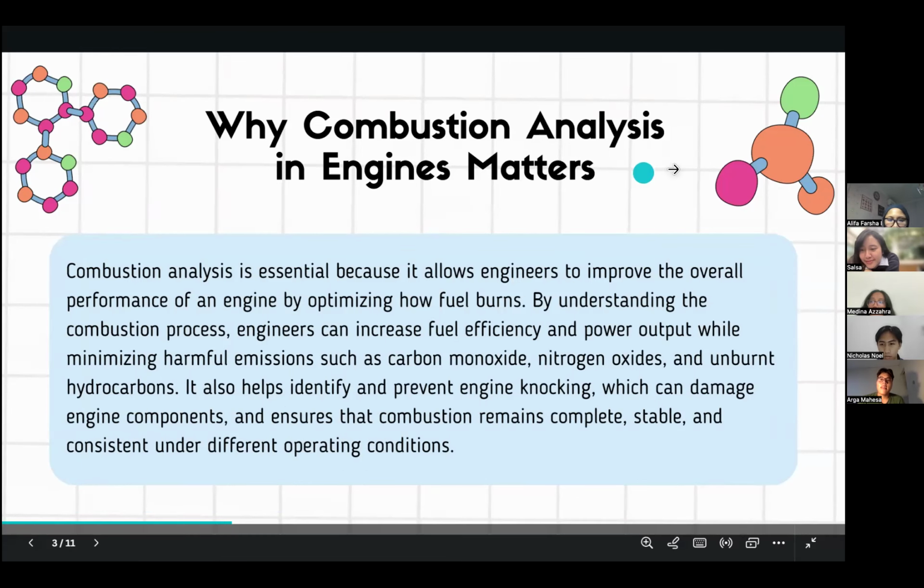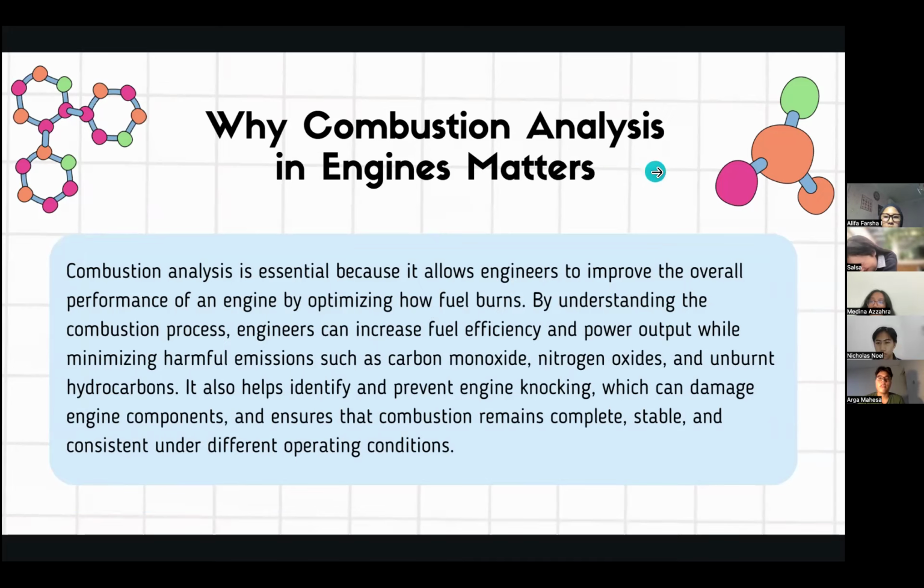Why combustion analysis in engines matters. Combustion analysis is essential because it allows engineers to improve the overall performance of an engine by optimizing how fuel burns. By understanding the combustion process, engineers can increase fuel efficiency and power output while minimizing harmful emissions such as carbon monoxide, nitrogen oxides, and unburned hydrocarbons. It also helps identify and prevent engine knocking, which can damage engine components, and ensures that combustion remains complete, stable, and consistent under different operating conditions.